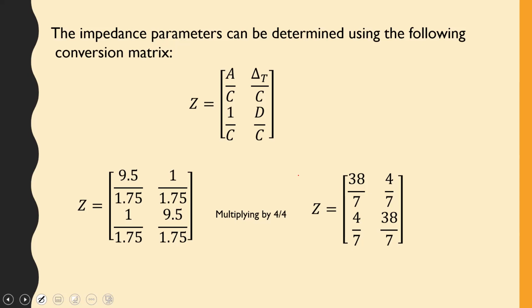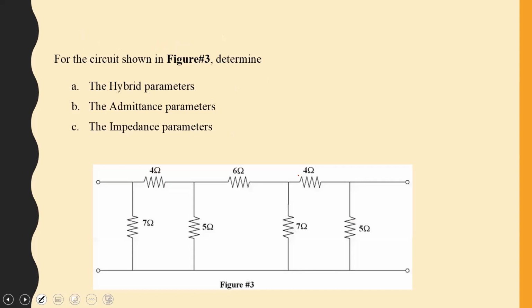If they are in parallel, for example, and what I have are the transmission parameters, no problem. I simply convert them to the admittance parameters, add them, and then if that combined system is connected in cascade, I find the transmission for the combined system and cascade it with the other stage. That's how we build out complex systems.